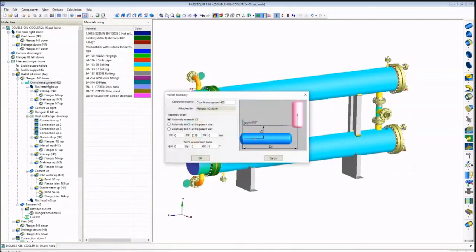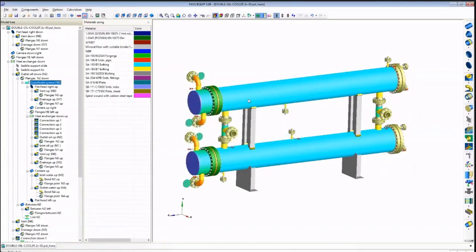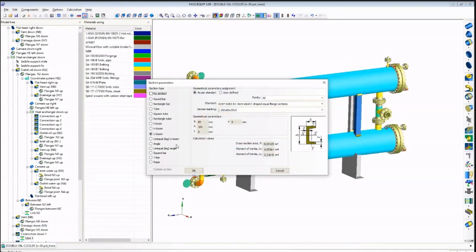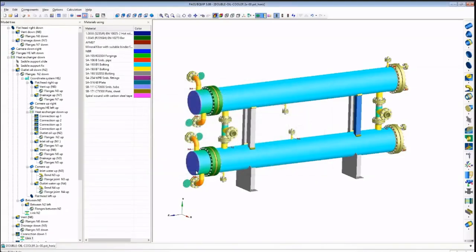After creating the lower heat exchanger, we create a new coordinate system with an offset relative to the base one. By copying the elements, we build the upper heat exchanger relative to the new coordinate system. Next, through the links, we connect the upper and lower heat exchanger into a single unit. In our case, these are 4 beams with U-shape.